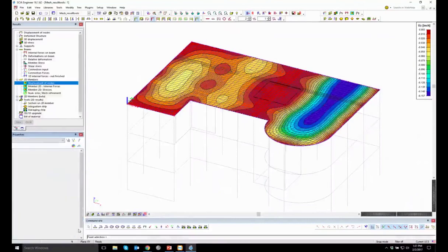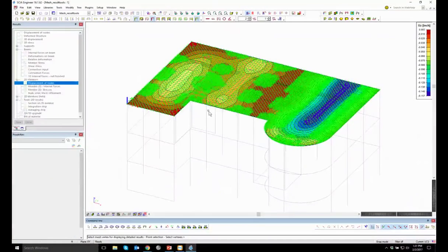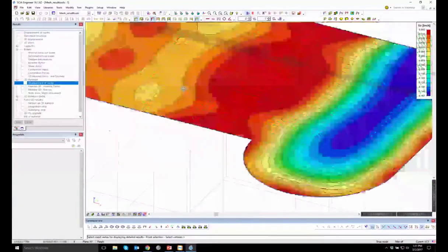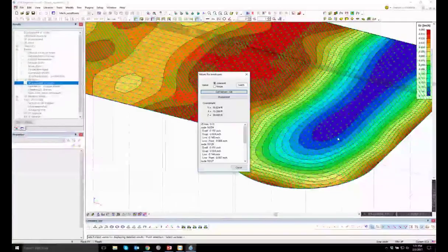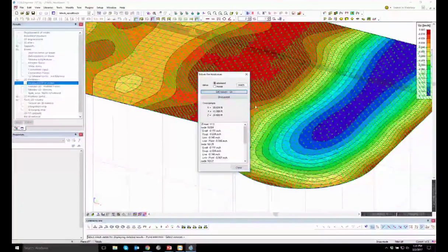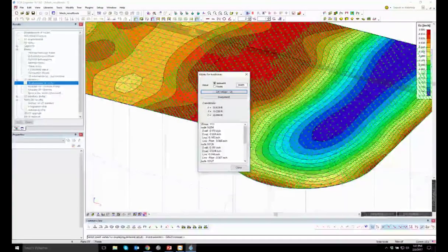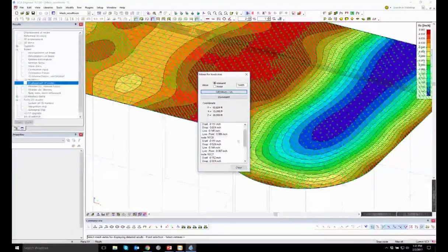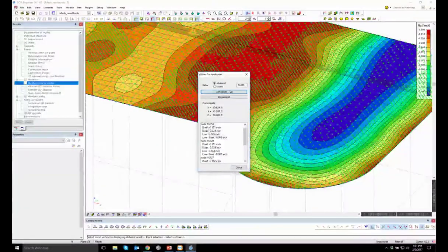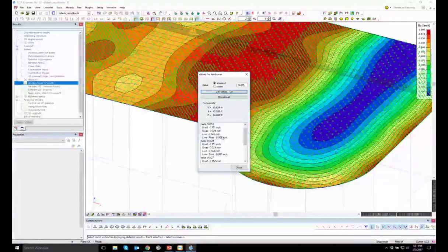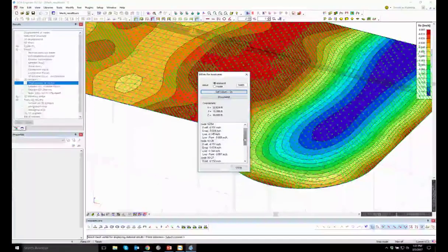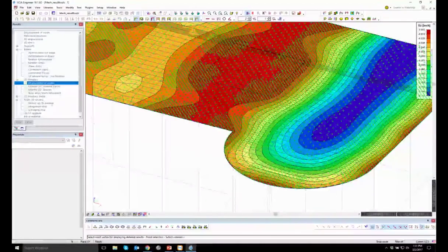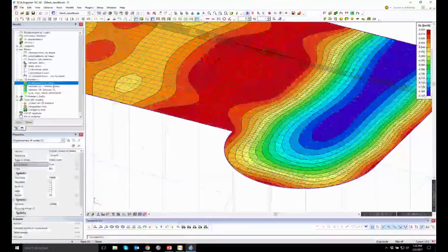Now I can choose to look at the detailed results in the mesh node. And so it's going to show me all the individual meshes, and I can go ahead and zoom in and say, hey, maybe we'll get something bigger over here. Say for this node, for that finite element, that's element 14,000 and some, at a certain coordinate location. These are the deflections that are happening. So based on self-weight, dead load, live load, point load, these are the deflections that are happening in that particular case in this direction. And so we can look very detailed at those results.